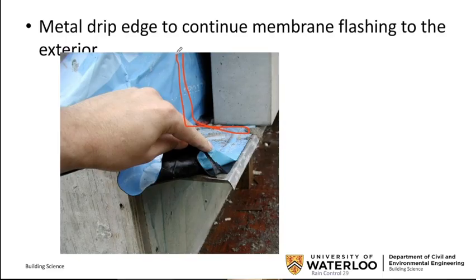The blue bit gives it strength, and the asphalt black backing is gooey, which gives it its water repellency, but also when you put a nail through it, the gooiness sticks to the nail, so it reduces the amount of leakage that could occur, and it gives it enough gooiness that it'll stick to the facer so that when you make laps and joints.